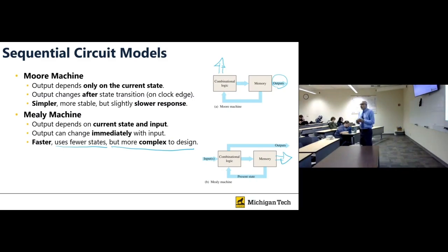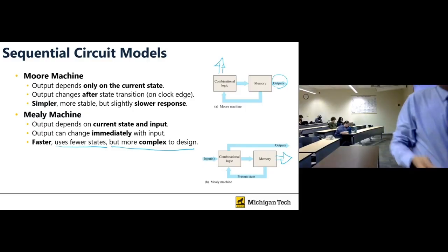For example, a heating system, like controlling the heater of a furnace, works like that. You have a sensor to read the temperature of the environment, and based on the previous information and what the user asked, for example, the user asked to set the temperature to 70 degrees Fahrenheit, the system considers the sensor input and makes a decision: do I need to turn the heater on or off?